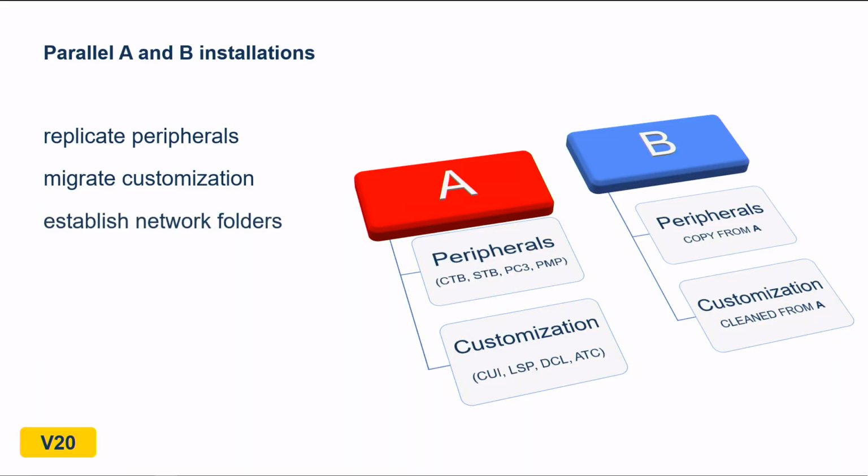Let's use BricsCAD as our impetus for a clean, fresh, quick start to get things running straight away. What I suggest always is to do a parallel mode of implementation. That is, get BricsCAD installed, tweak it, test it, and have it run in parallel with your existing CAD system. This is going to allow you to transition in a more orderly and gradual fashion. And if you saw our CAD managers on the comfy couch, when we were talking to Don Broussard, that's the approach that they took, and they found it much less disruptive to their company.